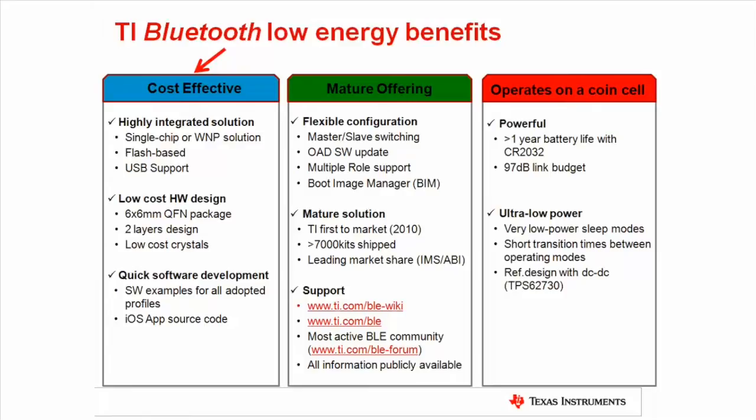We have also focused our efforts to have a low-cost total BOM with 2-layer PCB design, still enabling compact designs with the 6x6mm QFN package system-on-chip products we are offering. All software components including stack, profiles, example code, and mobile OS app code are available directly from TI without any cost or licensing fee.